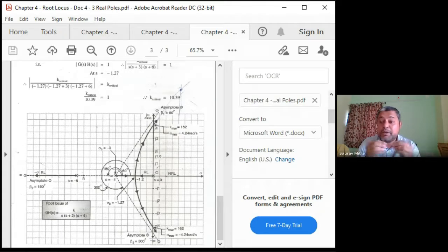It is not exactly the midpoint of the two poles. Okay, so it comes to calculation. Somewhere between minus 100 and minus 200 the meeting point will be. And if you increase the value of k further, it will shift onto the imaginary axis. And the minus 300 pole will start from minus 300 and keep going to the negative side. So this is actually the whole story of root locus.